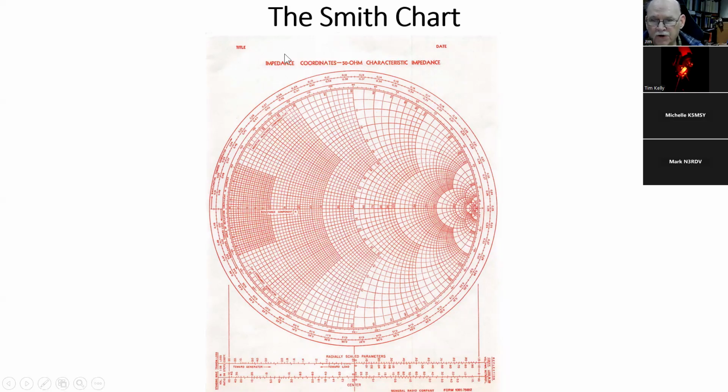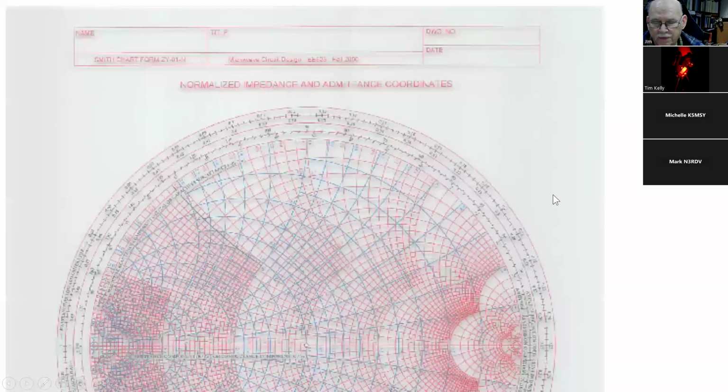And now this particular paper has been normalized for 50 ohms, so it reads 50 instead of 1. What I learned was this point would be 1.0. So you can plot any impedance, and then you can figure out how to use series reactances to get to a resistive impedance of 1.